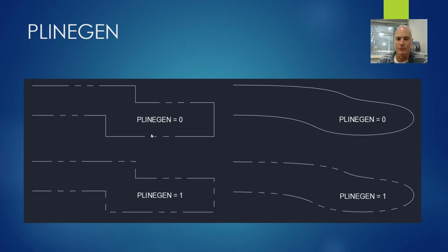But again, where this is really handy is when I've got a polyline that I've converted to a spline. Now I can come in and I can have those dashes evenly spaced, even though the object wouldn't normally have it. And this one here, because when I convert the polyline to a spline, there are so many breaks that it never allows that polyline to have that amount.